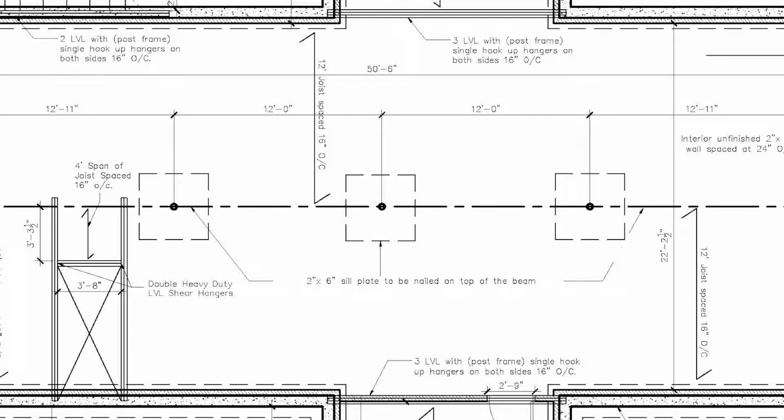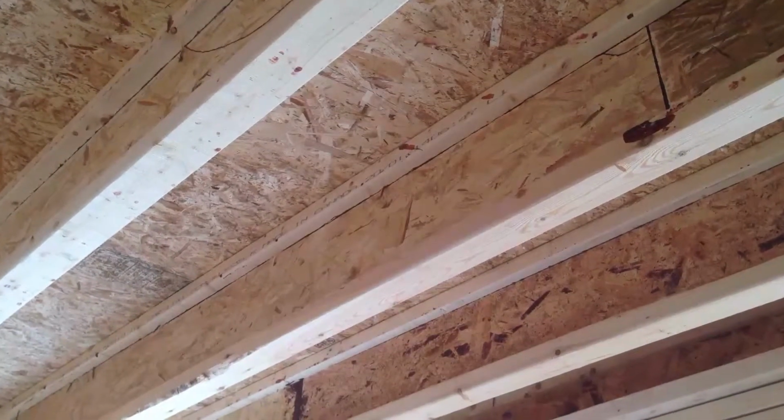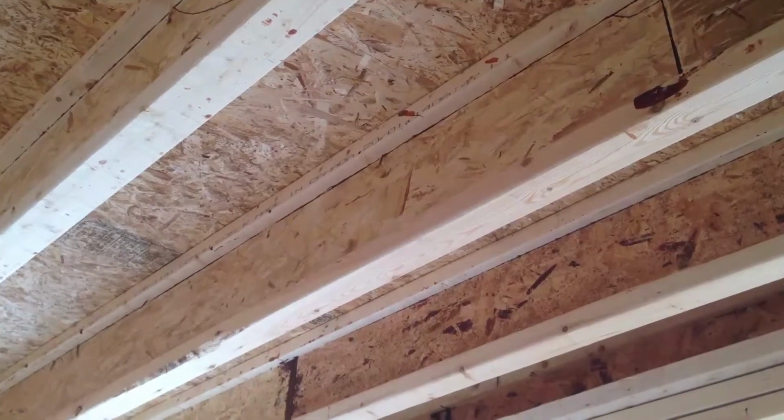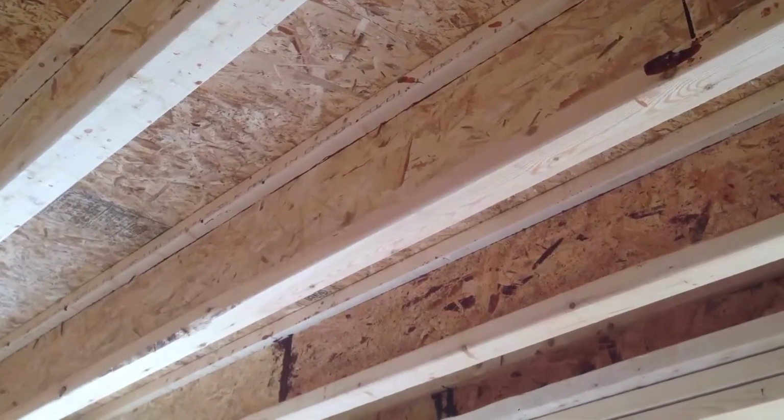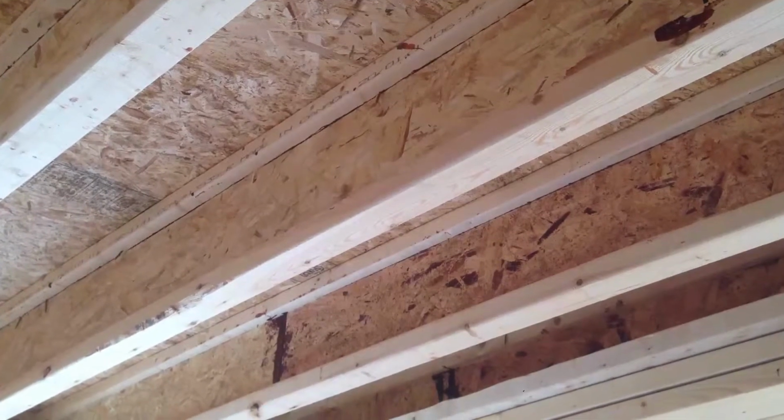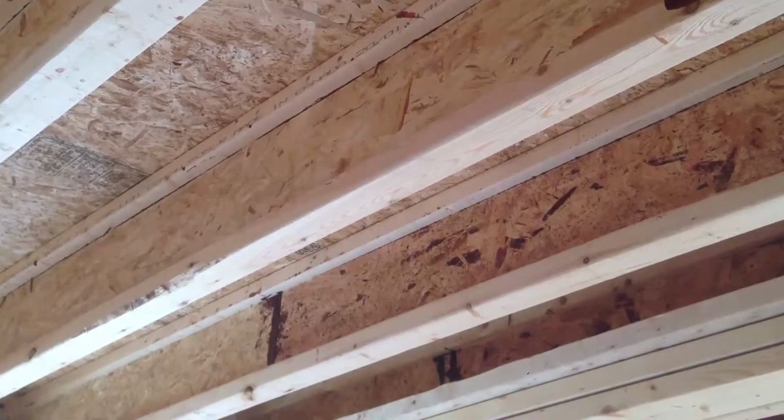They can also be placed between LVLs and foundation walls or steel beams. They provide the frame support and the subfloor and vary in shapes and sizes. They consist of standard lumber, however, TGI, truss joists, I-joists are more frequently used now than ever in residential buildings.